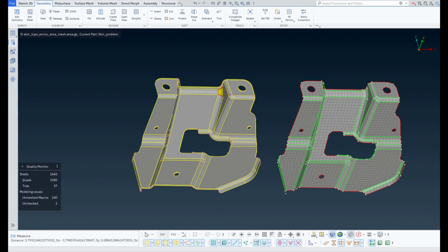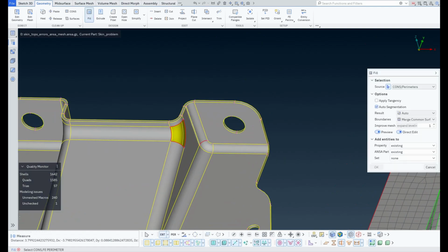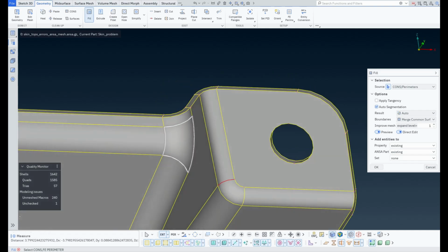These operations, although this is titled as geometry, this does not mean that the result is exclusively surfaces. Okay, and let me explain to you what I mean by that. The operation, for example, fill, to fill this gap over here among these cones. Okay, let's do it. Click, click, and click, and this would be the result. Yeah, the result is now surfaces.